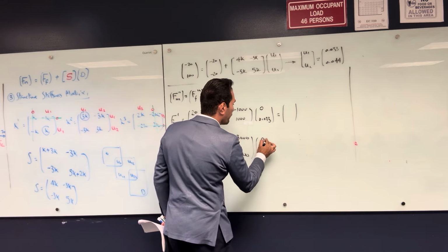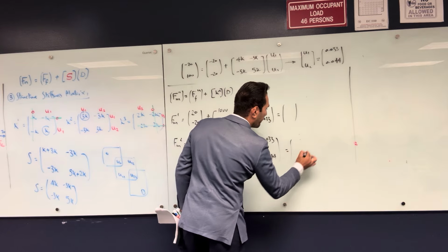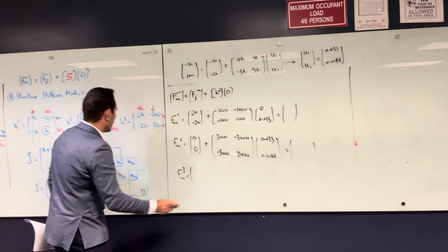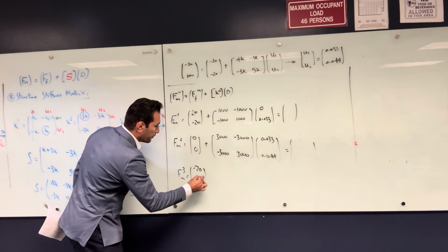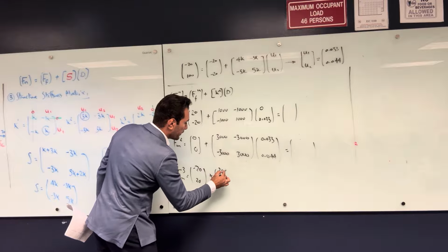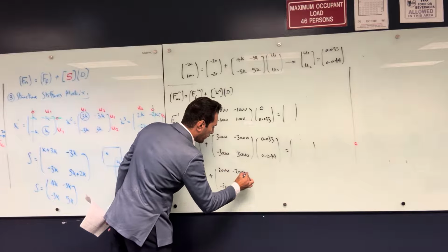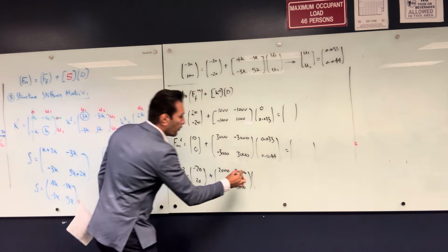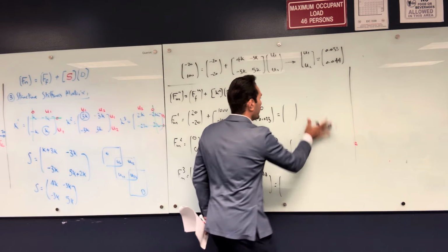And the deformation, I have U1 0.033 and U2 which is 0.044. And then I find what the value is. And then F member number 3 is gonna be the fixed end forces of member 3, which is negative 20 and 20, plus the stiffness matrix 2,000, negative 2,000 and 2,000, and all this multiplied by the degrees of freedom. At the first end, which is U2, we got 0.044, and the other end doesn't have any degrees of freedom. And I try to find what the final value is.